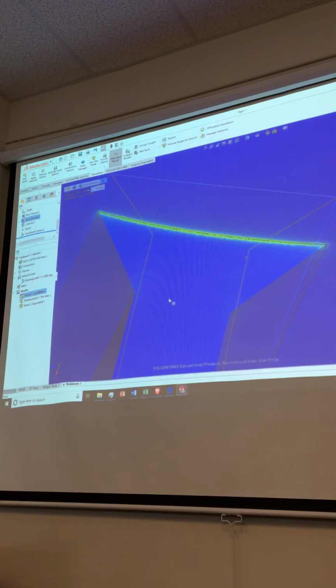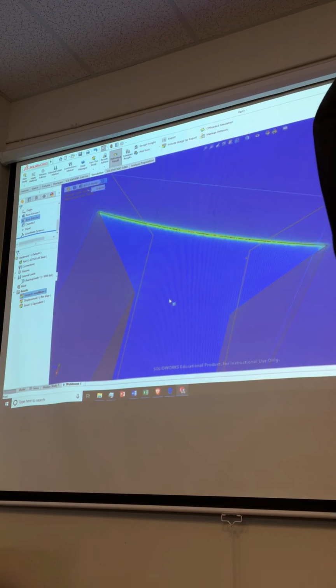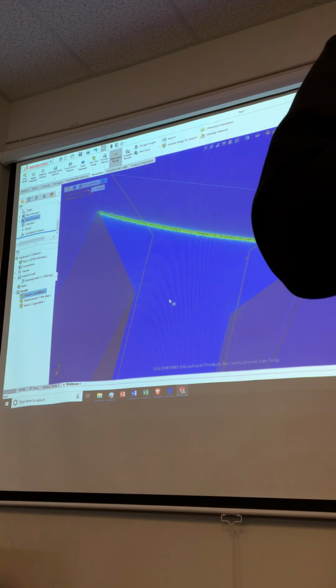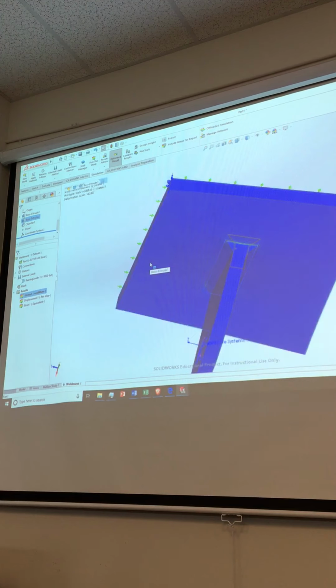They're all there. And that's not going to go away because it's a stress concentration. It's a square corner, right? What's it going to do? It's going to sit there and just do nasty things to me. So you're going, okay, we can do better than that, right? We can weld it up. Okay, let's go try to do that. We can go weld the darn thing up.